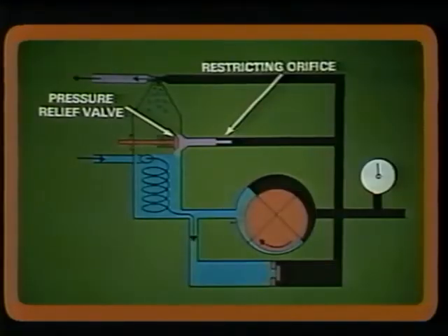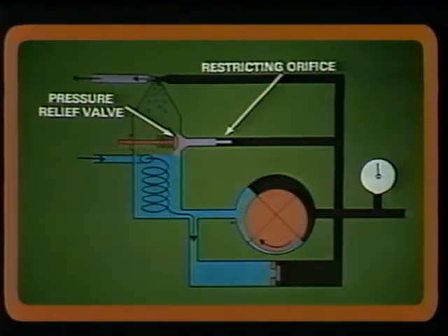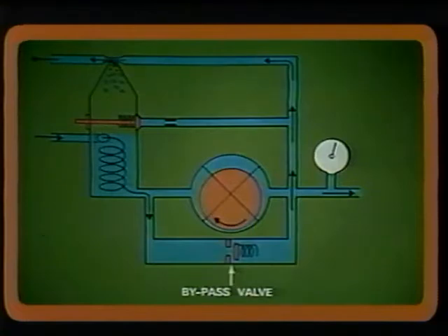When the pump RPM increases, this pressure is high enough to hold the relief valve fully off its seat, allowing the orifice to control fuel flow. A bypass check valve in the pump allows fuel under pressure from the aircraft boost pump to flow straight through to the cylinders for starting. But when the pump outlet pressure is higher than that of the boost pump, this check valve will automatically close.